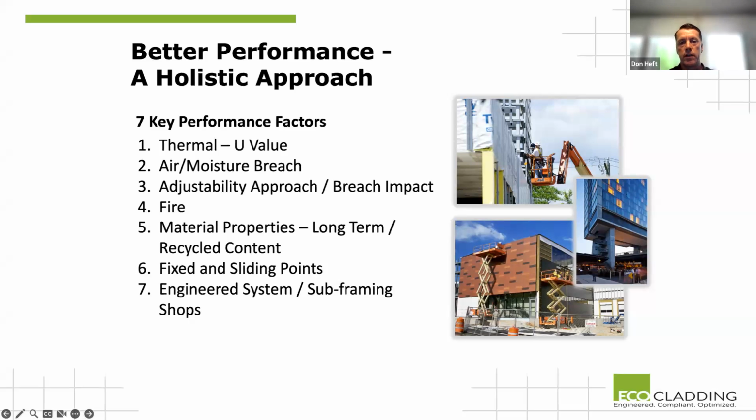And then there's the pure engineering of the system, making sure we have the fixing and sliding points, and looking at how that integrates with the wall and the backup wall, and how that integrates with the panel product. A lot of panel issues that happen out in the field are not necessarily a bad panel. It's typically something on the installation side, or it could be the system not being designed properly. So it's very important to tie together an engineered system and an engineered subframing through the engineering and shop drawing process.